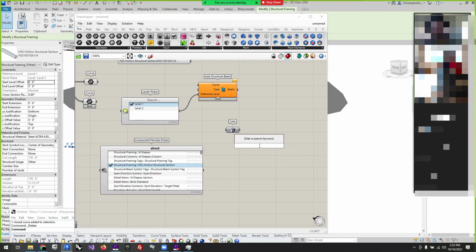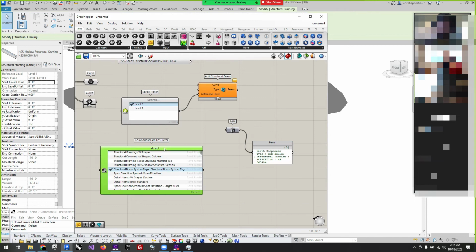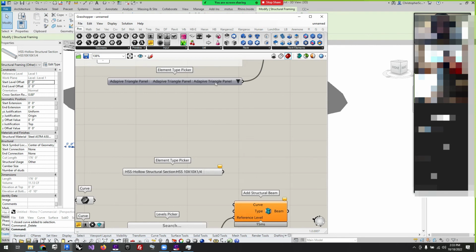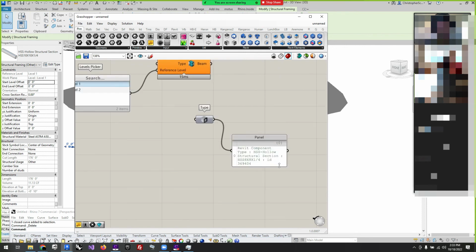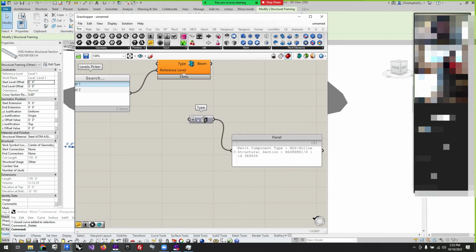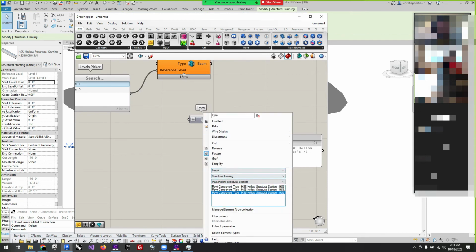And I can see that by opening a panel. For anyone who's curious how I got there, I actually do like that method quite a bit, but it's harder to see what that actually is versus here. I can see the name of that being explicitly drawn out by Grasshopper. Over here, it's a little bit more hidden, but the way to get to that type is if you right click in the middle section of the properties, you can come through and filter out all of the different elements that are in here with a pretty straightforward hierarchy of which one those are. So that's a nice way to do it.